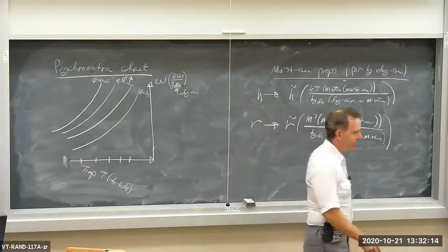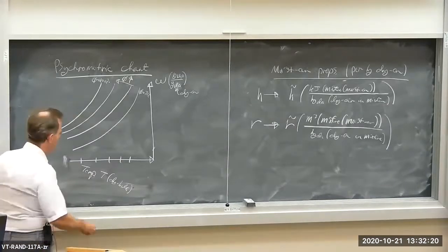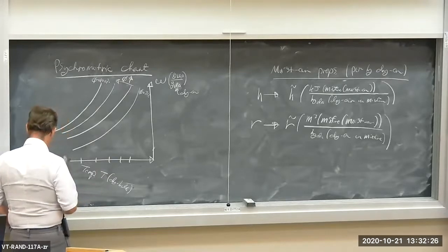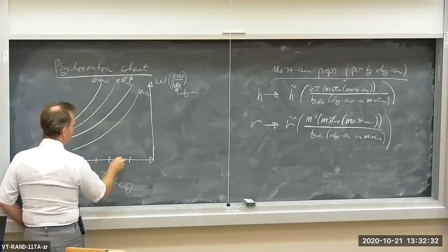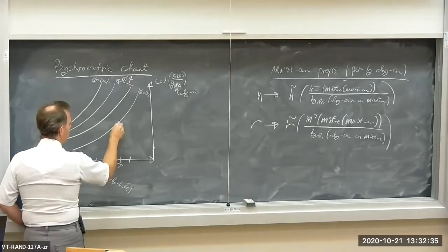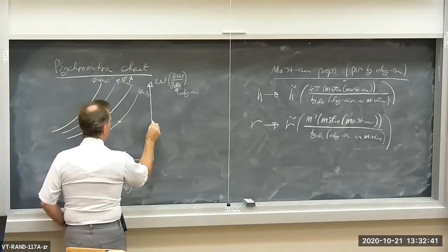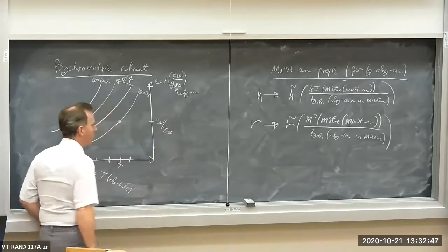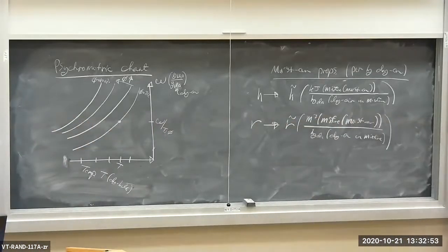So if you want to calculate the absolute humidity or the humidity ratio, let's say you're given a temperature and a relative humidity, all you got to do, so let's say this is your temperature T, and this is your relative humidity, is go to the constant relative humidity line, and there you have omega evaluated at temperature T and a relative humidity. So that's a fairly simple way to get absolute humidity or the humidity ratio using temperature and relative humidity.